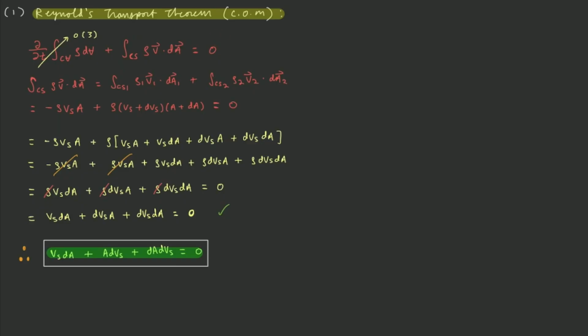And in another video, we will go into the specifics of Reynolds Transport Theorem and the ins and outs and intuitions and assumptions underlying that set of equations. But in this video, I'll just assume that you are familiar enough with Reynolds Transport Theorem to follow this as I've laid out here. So again, the equation is as we have shown here. And since we have a steady system, our time rate of change term goes to 0. And effectively, our conservation of mass just comes down to this term, which says our net mass flux through our control surface is equal to 0.